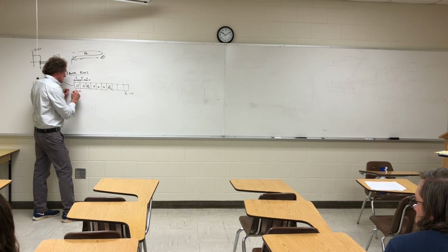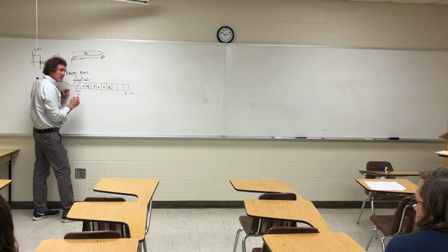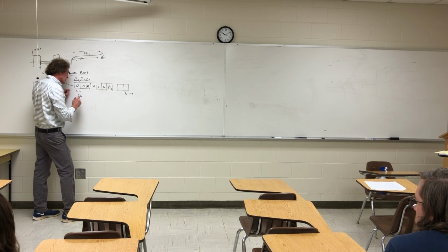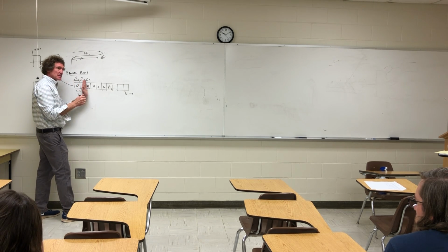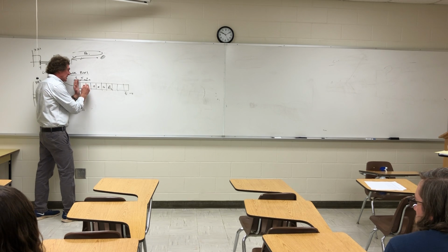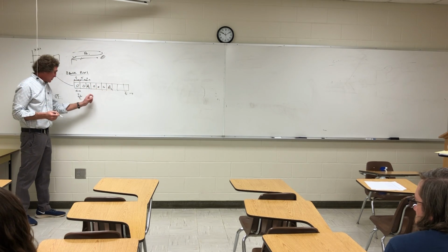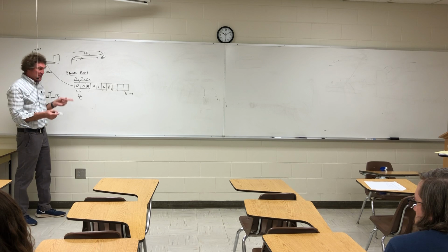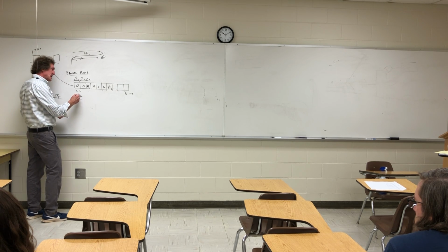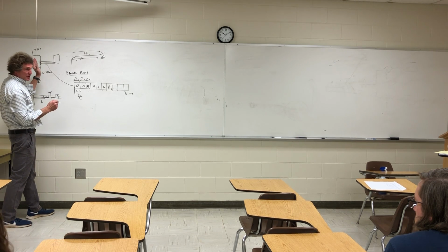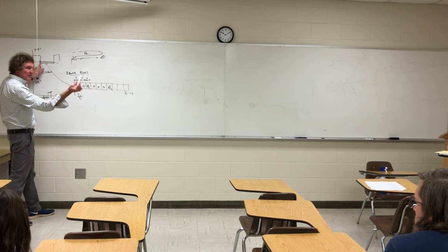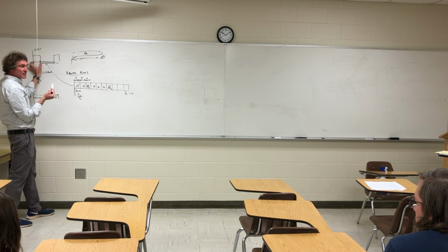Each range bin is width tau. Now think about the distance it corresponds to. That corresponds to tau c over 2, right? That would be the actual distance, right? Now when I'm looking at this, I can say, well, there's a target here, here, and I can look down here and see how far away it is. Now, something I also have to tell you, because that's the width, I have to also add on the actual, because remember, this is the end of transmission, now I'm listening, I have to take in the effective tau right here. But this is what's done.